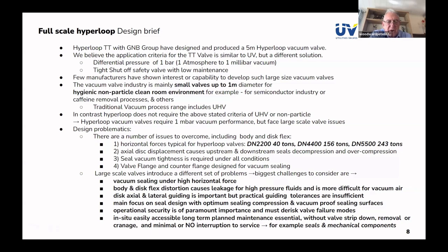The next point is the disc axial and lateral guiding is important. On the lateral guiding, we must be sure that the disc is brought down centrally. But most importantly is the axial guiding with this high differential pressure. You cannot impose tight guiding.